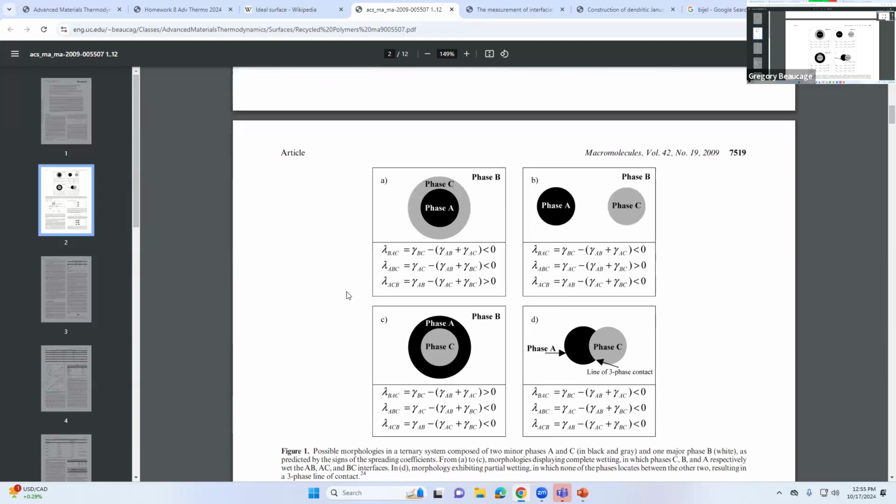So in order to do this, he has to make sure that the system's quiescent. In other words, it's reached kind of a local equilibrium state. I mean, equilibrium would be like A, B, C stacked up, and you wouldn't have any droplets. So this is a metastable equilibrium. But he has to be sure that the phases are spherical. He puts it through a mixer, so the phases are actually going to be stretched out. And then he anneals it for a while to get them spherical, so you can get that contact angle from that curvature thing. So that's kind of what he's doing here.